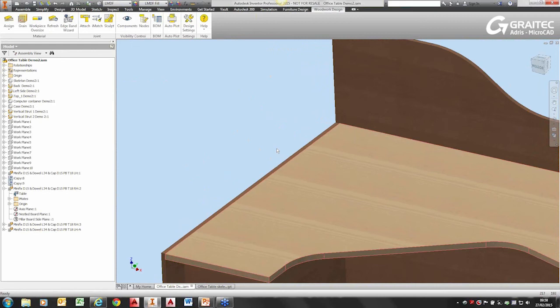If we move the hardware around, the holes will automatically move with the hardware because we've sculpted them using the Woodwork tool. So you can very quickly put in all of the hardware and all of the holes, and the holes will always be the right size because they're specified from the hardware. So you don't have to worry about putting the wrong size hole in. So for instance, screws, you generally want a small hole, and bolts generally a larger hole, and different joints you can specify whatever you want for your purposes.